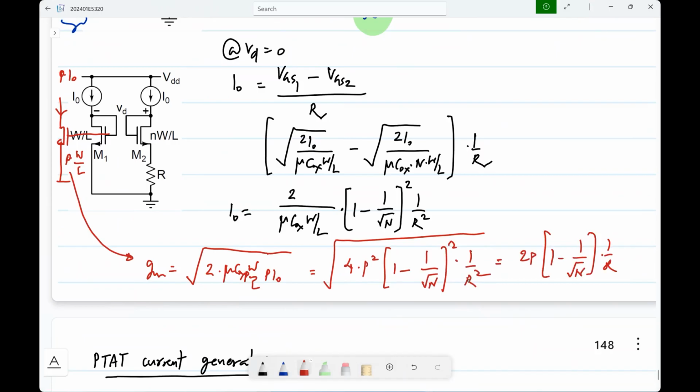So if you assume that you have a resistor which is constant with temperature, then GM also will be constant with temperature. Or even if R varies with temperature, if you make a common source amplifier with the same type of load resistor, the gain will become a resistor ratio and that will be constant. So interestingly, exactly the same circuit works even when you have MOS transistors in strong inversion. Weak inversion, it is expected. It's the same as bipolar.